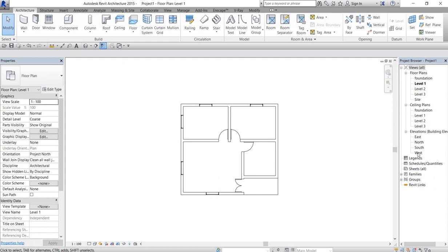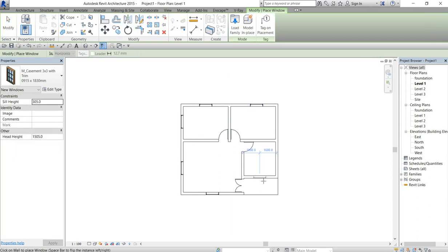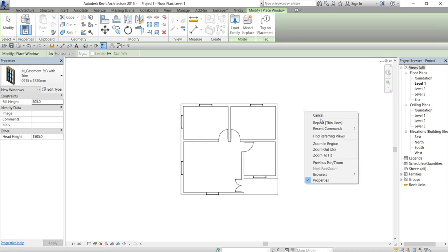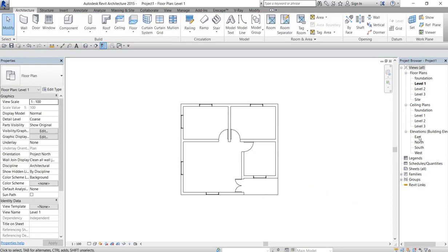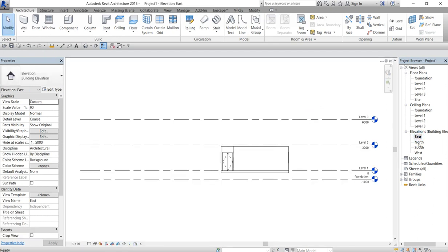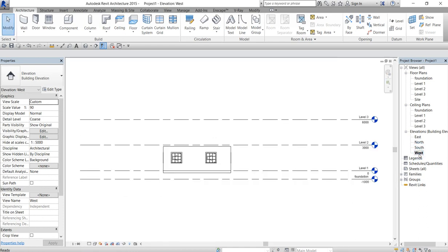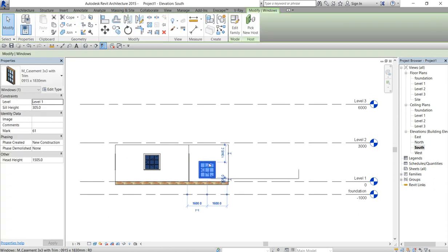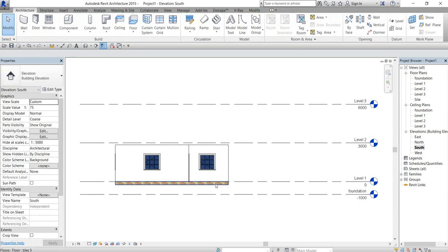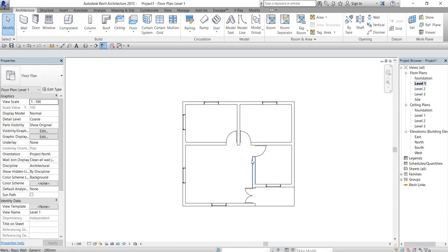So you can decide to check them around. There is no window here. Let's put window for staircase, maybe you put it here for putting sake. So you can start checking them on the project browser by looking at the elevations, looking at all the elevations all around. Something is wrong here. So like this one, you have some issue. That's why I said you should do that. So check it and press 2100. So it snaps itself back to normal. So that is how you work on the normal plans for the ground floor.